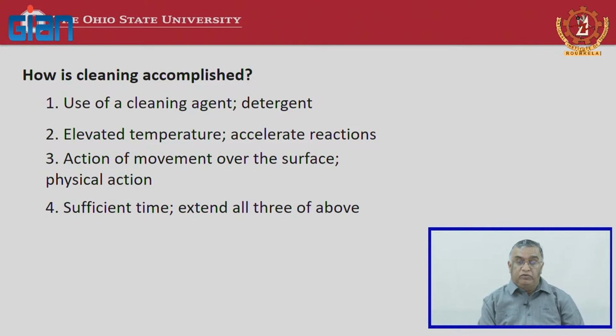So, what do you do for cleaning? Basically, you use a cleaning agent, often a detergent with water, so that you are able to clean the surface. Oftentimes you can clean by pumping water at room temperature, but it will be much more effective at a relatively warmer temperature, say 60 or 70 Celsius, depending on the operation.